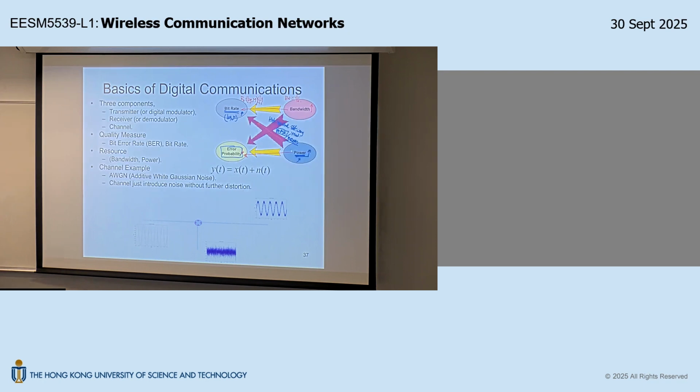They are all based on coaxial cable. If you work for a cable TV company, you may need to design how much power amplifier you need to install, and you need to calculate the link budget, whether the signal-to-noise ratio at each household would be good enough to receive the constellation. In order to maximize the bit rate, because TV broadcasts require huge bit rate, you want to use a very large M for modulation. So this is the modulation system in some of the modern cable TV design.